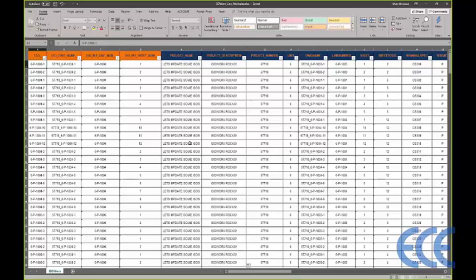And with this line list, all we're looking for are a couple main items for ISOWorx, and then the rest of it comes down to whatever you have in your AutoCAD title block. So these first 4 columns are required by ISOWorx depending on the settings that you guys are using. The first one is simply the tag or the line number that you have inside the model. So this will line up directly with the model information you have. The next column is what you would like the name to become.